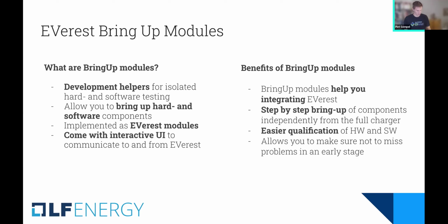So what they do is make it very easy for you to integrate Everest, because you can test your integration in parts. Start with an integration of a power meter or a power supply or whatever component you want to integrate, and bring up Everest step by step and independently from a full charger development.